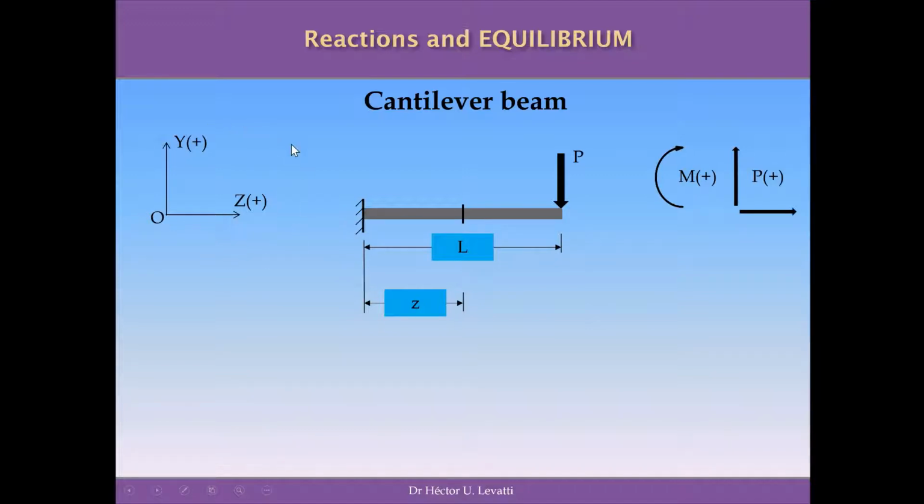So these are the conventions in terms of displacement. Displacements are positive in the horizontal direction if they are going to the right, and in the vertical direction if they are going up. Moments are positive when they are clockwise, forces are positive when they go up, and forces are positive when they go to the right. So this force P on the structure is negative, evidently.